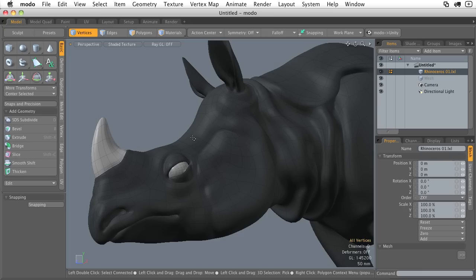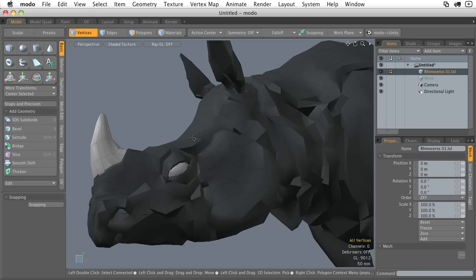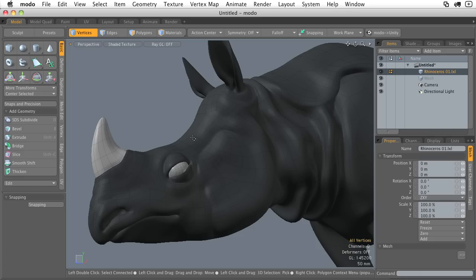At the core, though, we still have the exact same polygonal cage. If we hit tab again, we can see that the model itself is still basically constructed off of the exact same polygons that we originally had. So the tab key is a toggle, so we can go back and forth from our polygonal cage to our subdivision surface just by hitting the tab key.